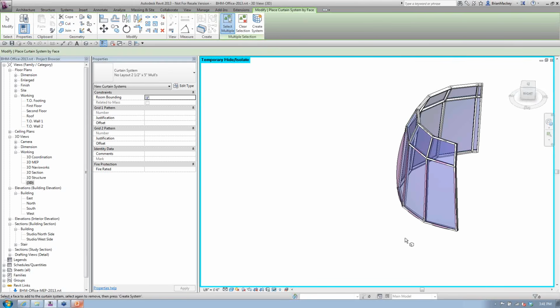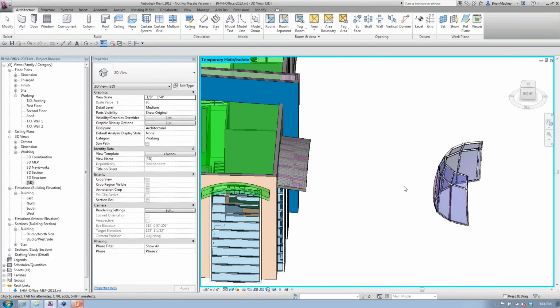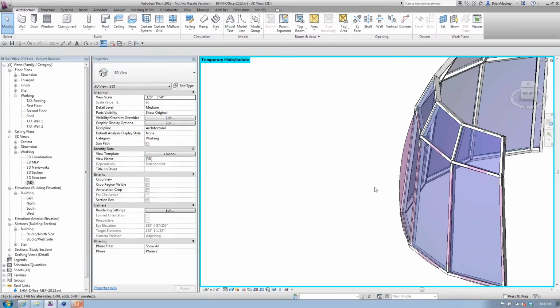And then Edwin, kind of a follow-up to his question on the curved deck, and to clarify, you can't create a curved floor, only a curved roof. You're correct, Ed. We can only do curved roofs, but roofs don't have the composite metal deck. That's where I got confused. You only have composite metal decks on flooring, so you don't get that option with a roof anyway. So that hopefully gets it for you there, Ed.